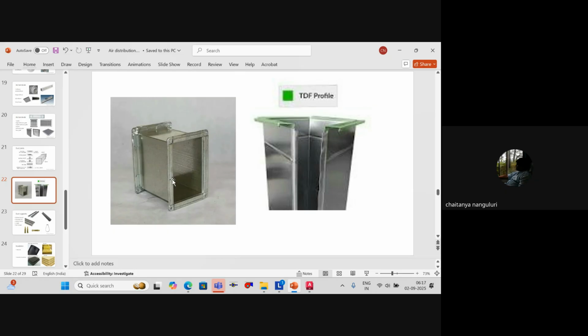And you will connect it. So you apply a gasket over it, and then on both the sides you add multiple bolts. This is 99% of your factory fabricated ones. You will get this one. But in a few locations, what will happen?